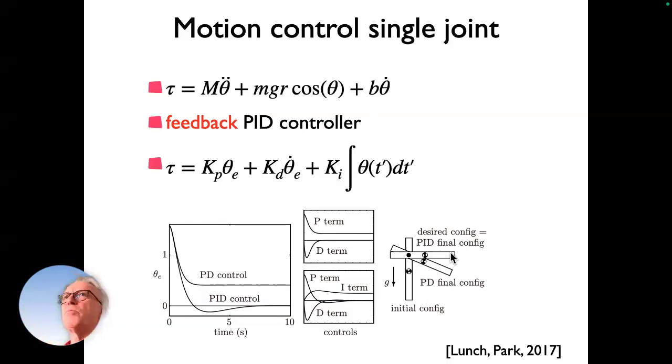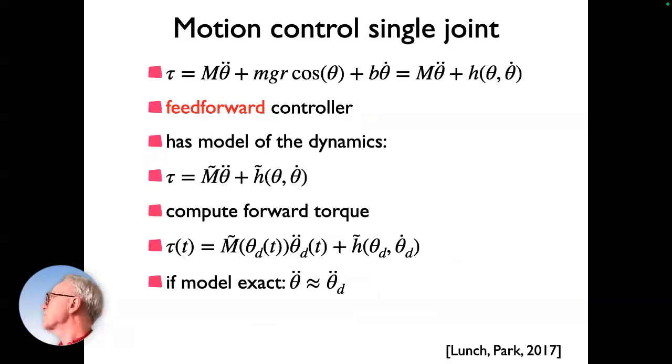I should have thought about this problem and computed the torque and have some extra term just for compensating for gravity. That would actually be the correct, better solution. And so this is sort of the generalization of that one that compensates for dynamics. So let's say there's no feedback. I could just control this without feedback, then I don't have these funny problems, but just compute what kind of torque I need to achieve the state. And this could be done by having a model of the dynamics.